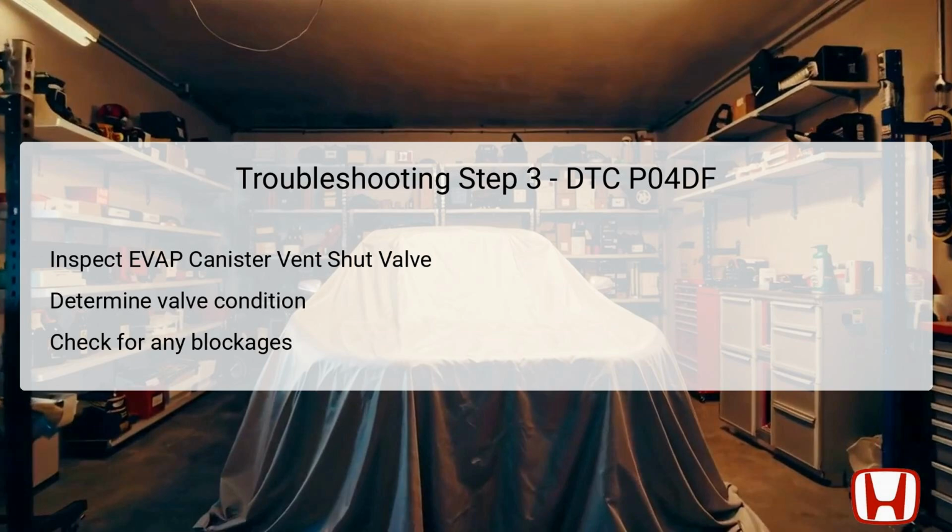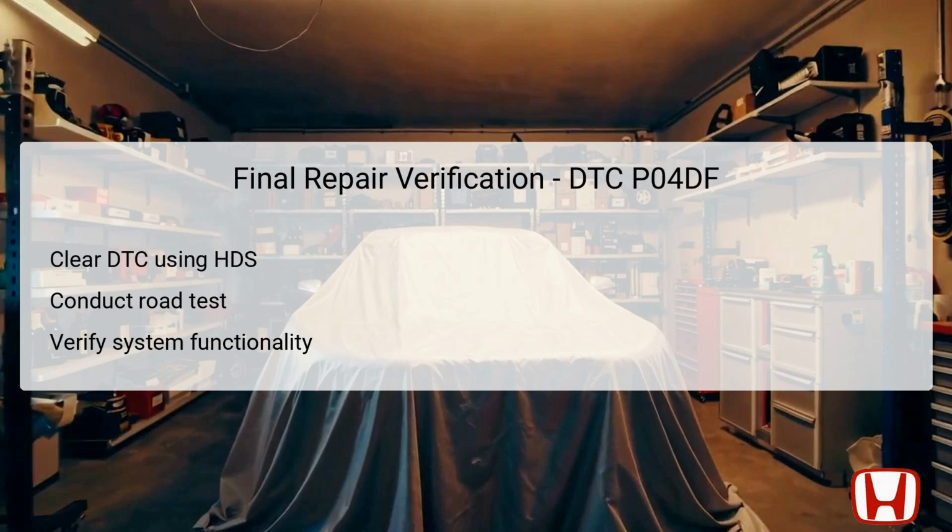to register. During this inspection, look for any physical obstructions that may prevent the valve from closing or opening as intended. Testing should include functionality checks through the HDS to confirm the valve's operational status. Should this inspection reveal that the vent shut valve is malfunctioning, it will require replacement to restore proper function to the entire system.